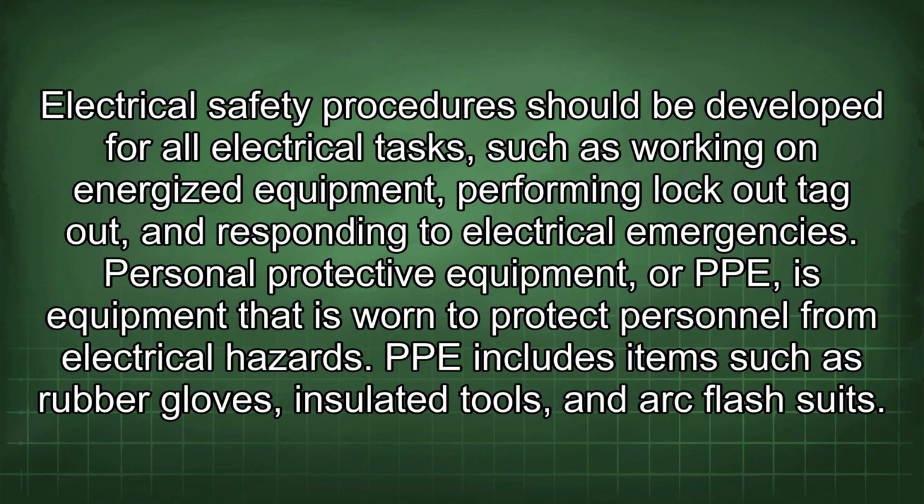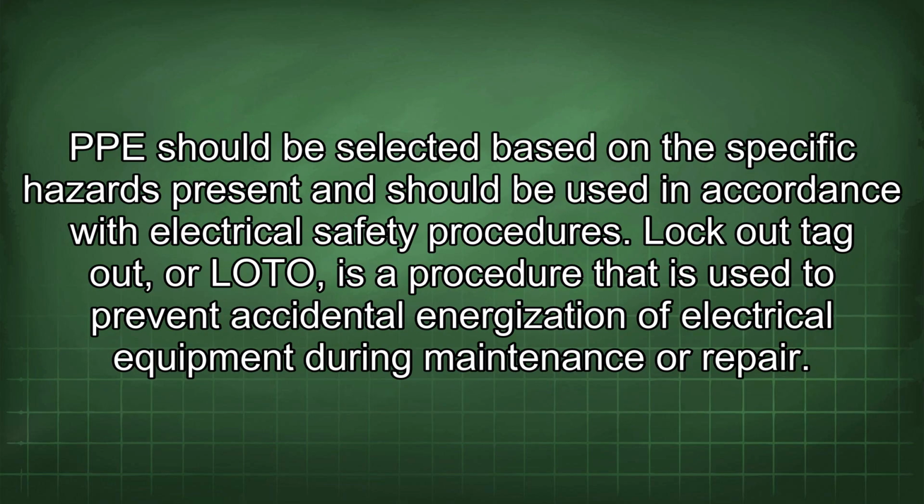Personal protective equipment, or PPE, is equipment that is worn to protect personnel from electrical hazards. PPE includes items such as rubber gloves, insulated tools, and arc flash suits. PPE should be selected based on the specific hazards present and should be used in accordance with electrical safety procedures.